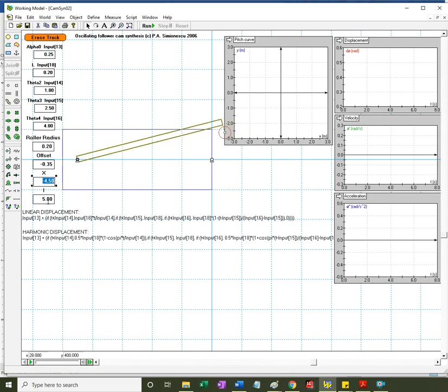Okay, and then all sorts of adjustability that I can play with. So size of the cam, as well as the pressure angle, as well as the undercut. And if nothing else, you can of course change the follower motion. A linear displacement or linear follower motion is more prone to undercut than a higher order one.